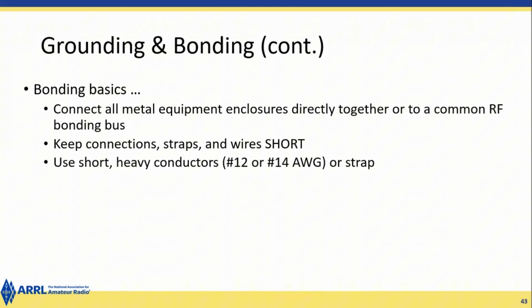D. Which of the following direct fused power connections would be used for a 100-watt mobile installation? The battery using heavy gauge wire. It would be A, directly to the battery with heavy gauge wire if you can. Why should DC power for a 100-watt HF transceiver not be connected to a vehicle's auxiliary power socket? Socket may be inadequate for the current draw by the transceiver. B. Which of the following most limits an HF mobile installation? I think the efficiency of the electrically short antenna.